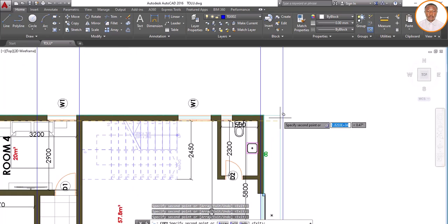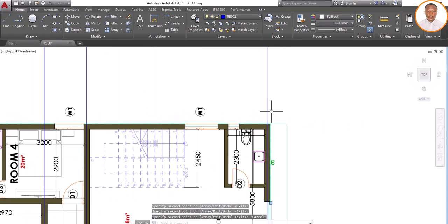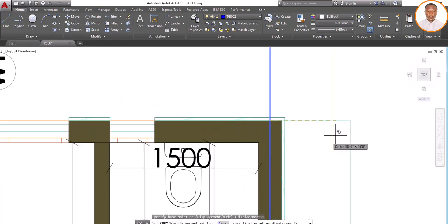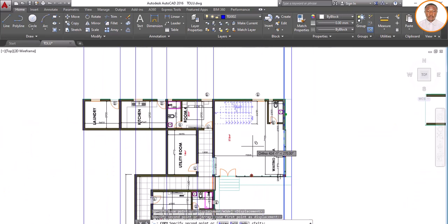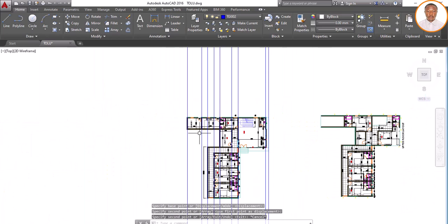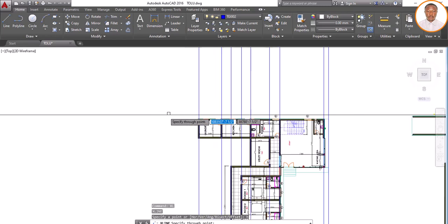Okay, I think this place is cantilever. This is cantilever, so I will escape and copy this and also move it from the center here to this edge here to show my cantilever. Okay, that's fine. All right, so now what I'll do now again for my horizontal, I press XL, enter, H, enter. So I also come here again.